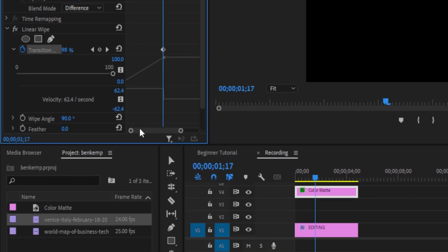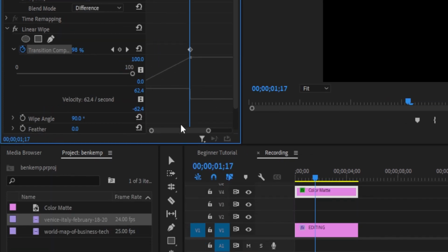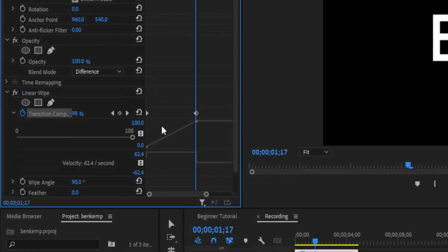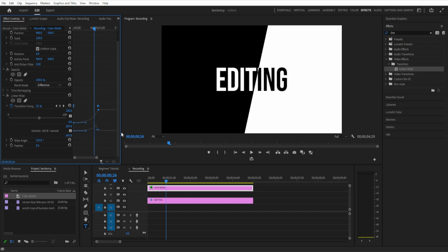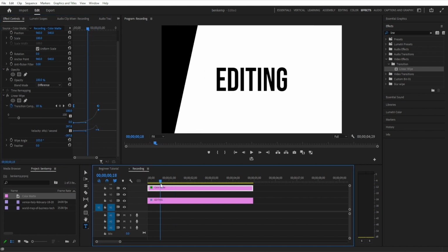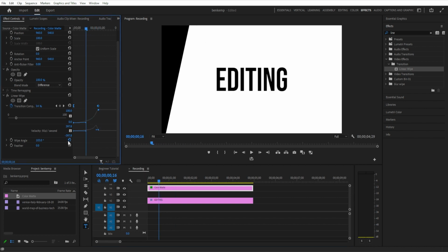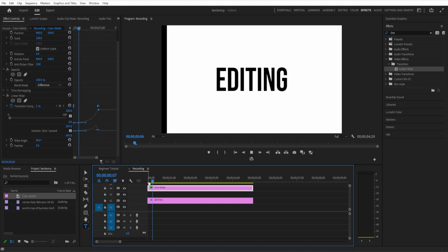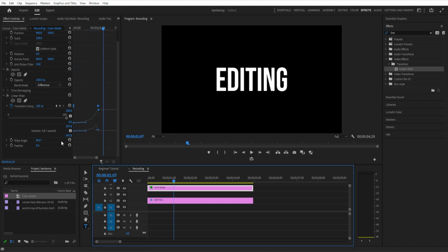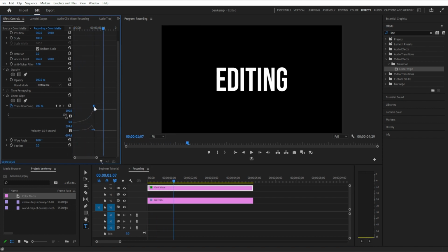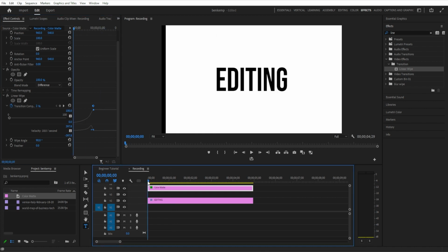This panel can get a little bit finicky, but if I highlight any keyframe, I get these little handles I can pull on, and I'm just going to ramp the keyframe a little bit. So I'm adding some velocity. So it starts slow and then quickly finishes. And this is going to make your animations look a lot more professional. So maybe that's a bit much, but you can tweak it. But if you see play, it starts slow and then whoosh, it gives it a nice feel.